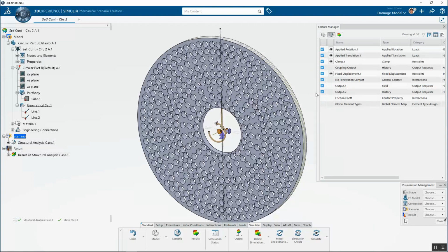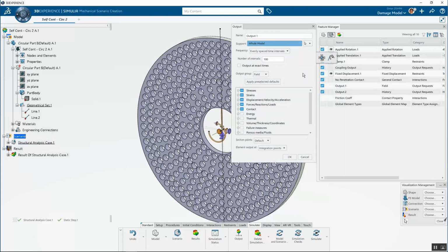With respect to the output, it's similar to SolidWorks in that this is a nonlinear analysis. I'm making the assumption that my load is applied from time 0 up to 1. It's going to incrementally step from 0 to 1 for all of my loads that are applied. I'm telling it that I want 100 results stored. So basically, a result stored every 0.01 pseudo time step, right?